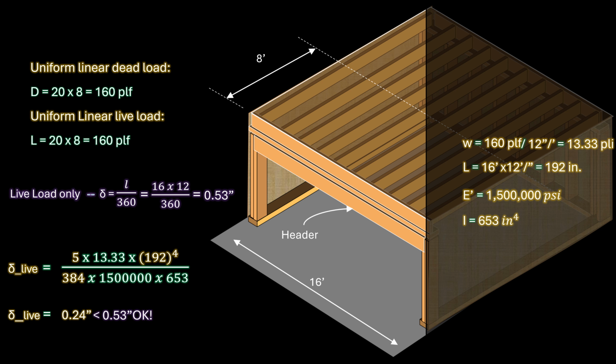Please note that by using the elastic modulus provided in the NDS supplement, the deflection we have calculated includes a shear deflection component in addition to the predominant bending deflection component, even though the deflection equation that we have used is based on the Euler-Bernoulli Beam Theory.